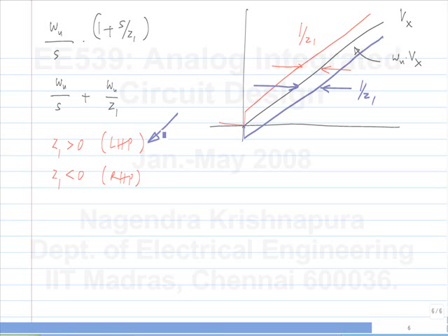Maybe you won't be able to compensate it exactly, but you'll be able to compensate it at least partially. So I think you've heard of the term pole 0 compensation. That's the idea there. You add a 0 and maybe you will modify the pole a little bit also, but the net effect of 0 and the pole should be such that the delay is smaller than before. And the right half plane 0 is definitely bad news.